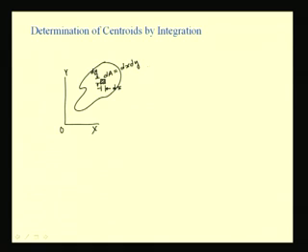So, I find the equivalent x bar A as the integral of x dx dy, where A is equal to the integral of dx dy, and this is a double integral, because you have to integrate for the limits in x and y.